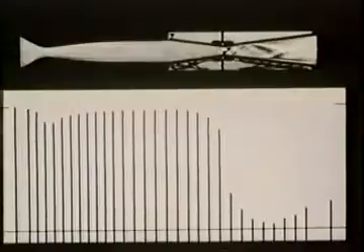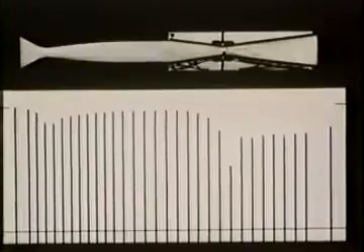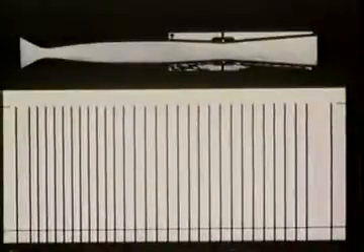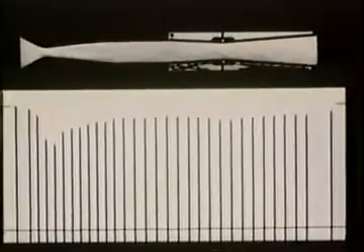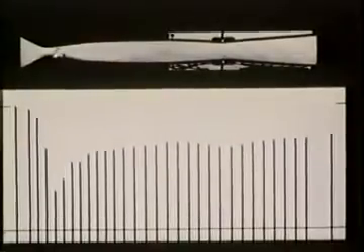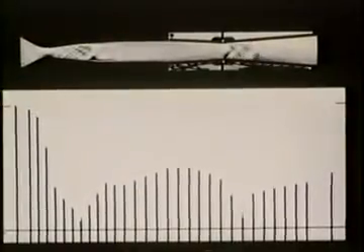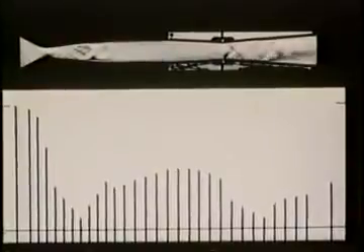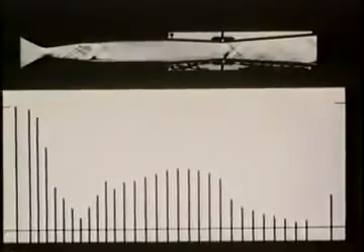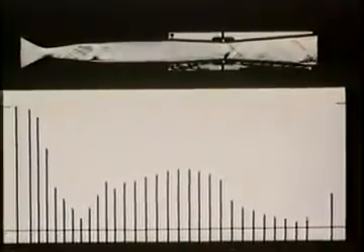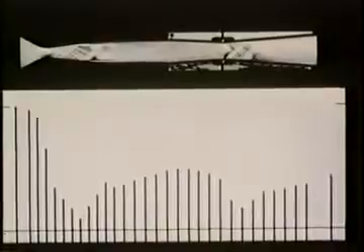Now let's make the second throat slightly larger than the first. The first throat chokes, and a shock wave appears in the nozzle. Then the second throat chokes, and we can no longer affect the first shock wave, only the second one. The channel is now said to be blocked, with the first shock wave trapped in the supersonic nozzle.